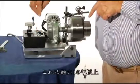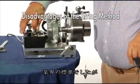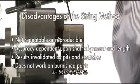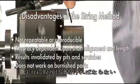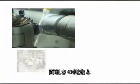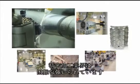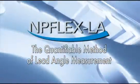Although this string method has been the industry standard for over a decade, it has widely known disadvantages and failings. It has proven to be qualitative rather than quantitative because the results can vary from operator to operator and depend heavily on the level and wobble of the shaft at setup, as well as the surface finish of the shaft during measurement. The precision machining community is currently underserved in metrology for the measurement of surface roughness and, more importantly, lead angle of a dynamic shaft seal interface.